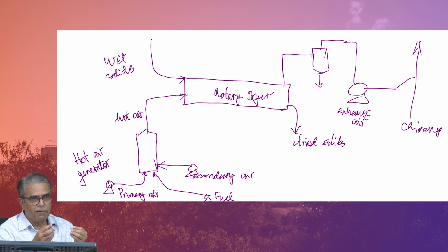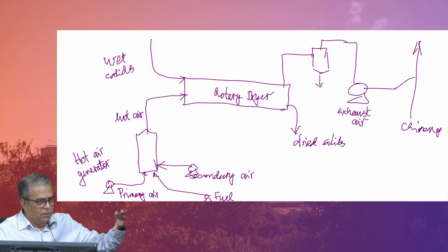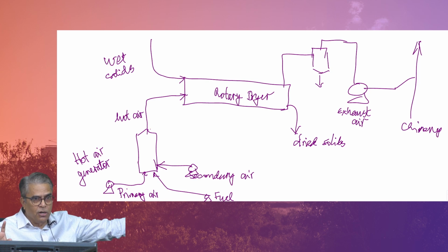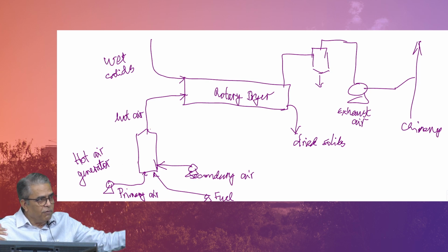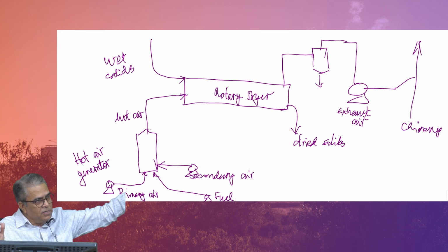If it is a sticky fibrous material, very fine powder, it is a bit hard to use it in a rotary dryer. The arrangement is, there is a cylinder, the diameter is typically about 3.5 meters, big size, and about 20-22 meters long, huge ones, and it is slowly rotating at about 3 to 5 rpm, and it is slightly inclined about 3 degrees with respect to horizontal.